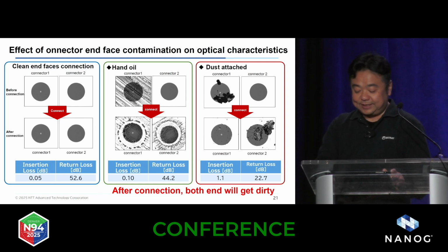As you can see, there is a slight decrease in the optical characteristics. Also, even when connector 2 is clean before connection, dirt will be transferred to the other connector. So make sure to clean both sides before connecting.